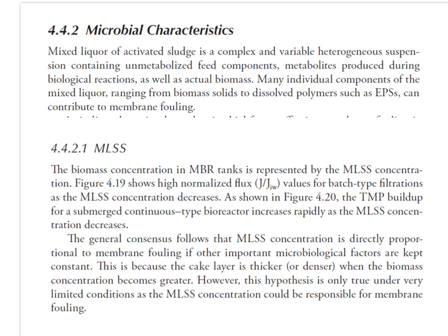We also have to look at the dissolved polymers such as EPS, because they are closely related to membrane fouling. The first factor that we have to look at is MLSS, which is a very important biological operating condition. This is actually the biomass concentration in the MBR tank, and it is closely related to fouling.